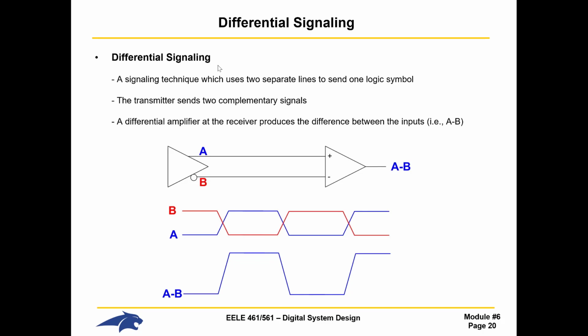And then what made it even weirder is that the way that it changed the impedance of your line varied depending on whether that neighbor was transitioning up, transitioning down, or was held at 0. And so it made it really difficult to terminate anything because your impedance was changing. So we did not look at that in vain. There was a reason that we went through all that derivation for Z odd and Z even, because ultimately we are going to use all that. It'll all come back when we start thinking about this new type of signaling, which is called differential signaling.